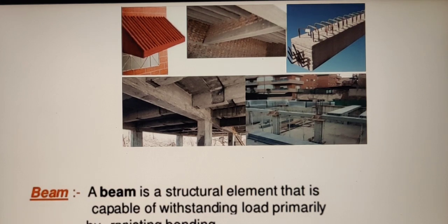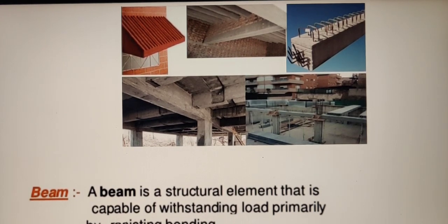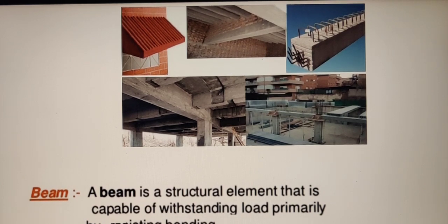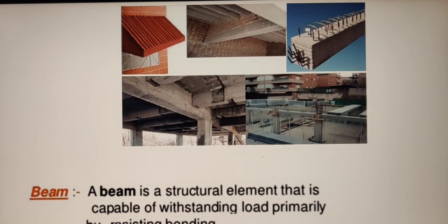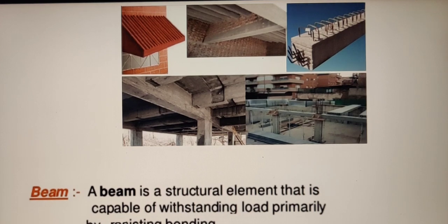While analyzing the beam, analyzing means you have to calculate the support reactions developed on the beam due to the external loads. You have to remember that the beam is a system of coplanar non-concurrent forces. So we have to apply the three equations of equilibrium: sigma Fx is equal to 0, sigma Fy is equal to 0, and sigma M is equal to 0. That is, you can take moment about any point.